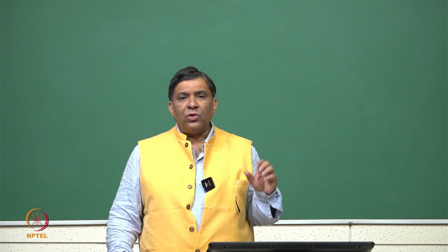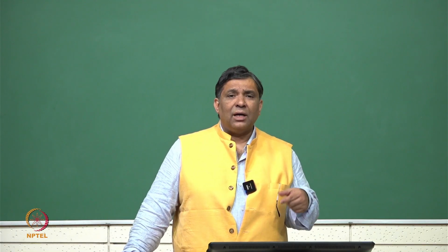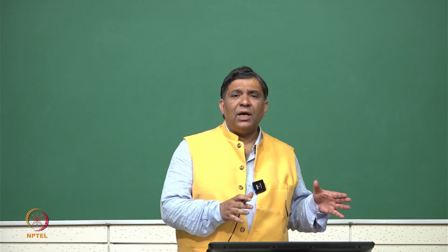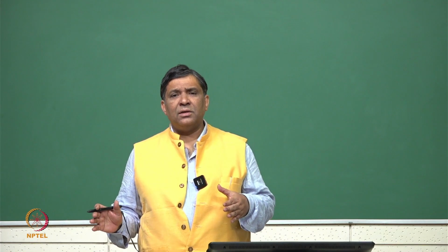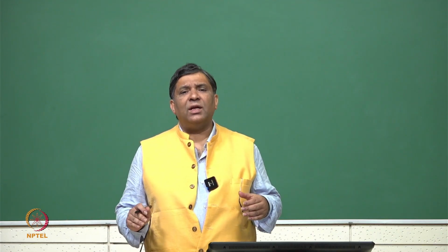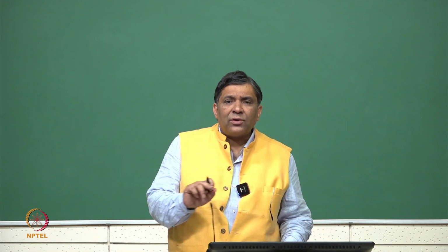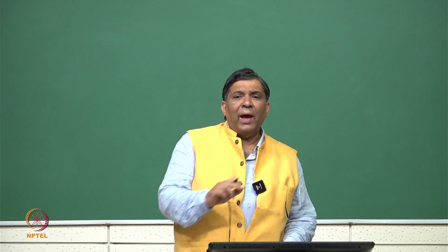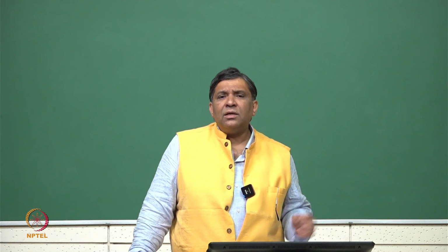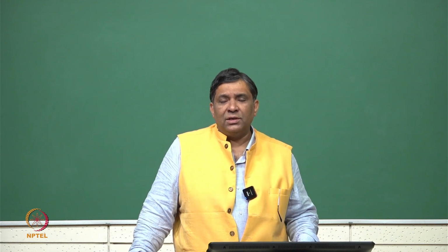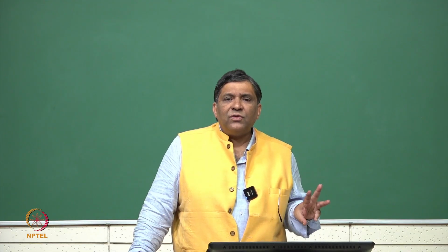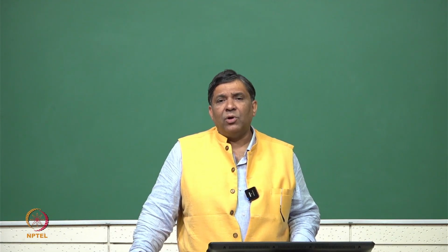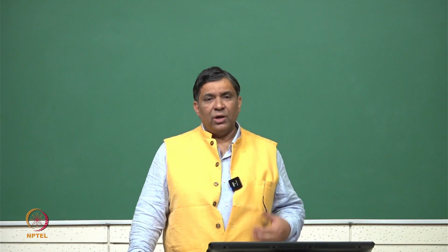But here in thermionic generator there is definitely a hot emitter and a cold collector, but the energy is generated when electrons flow from emitter to collector, the collector collects the electrons and gives them back through the circuit, and there is an electrical energy generation. So, this is a basic difference between a thermoelectric generator and thermionic generator or thermionic converter.